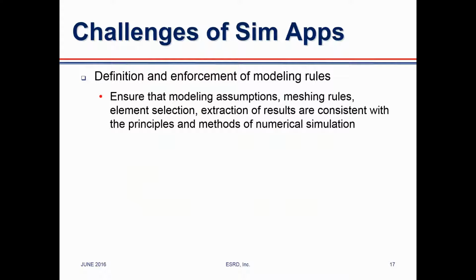So what are the challenges in the development and deployment of simulation apps? The first one is the definition and enforcement of modeling rules. It's important to ensure that modeling assumptions, meshing rules, element selection, and extraction of results are consistent with the principles and methods of numerical simulation, always keeping in mind that the end user may not be a specialist.